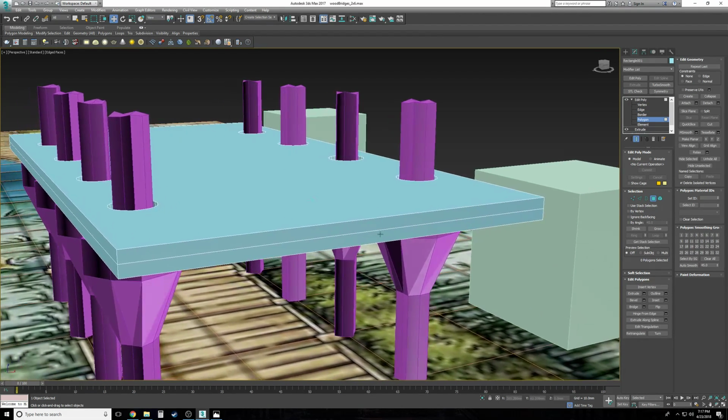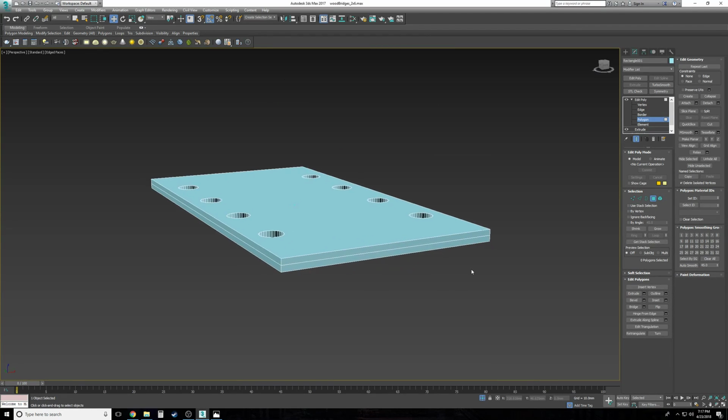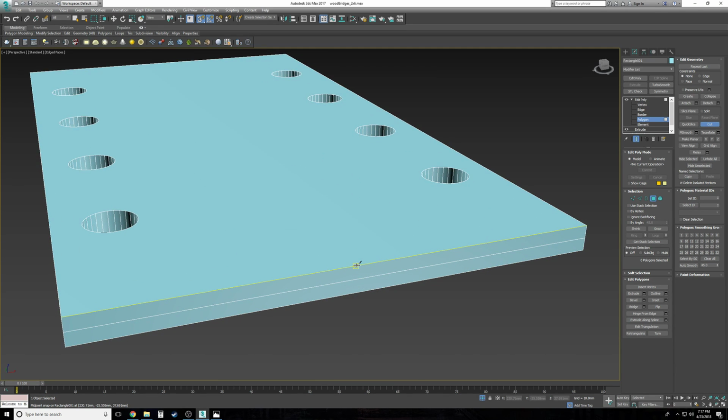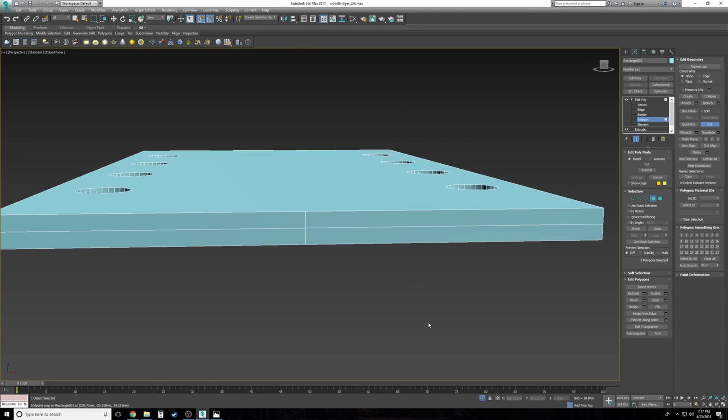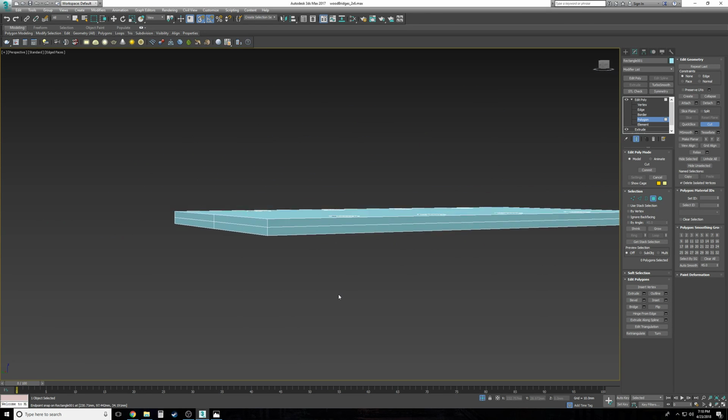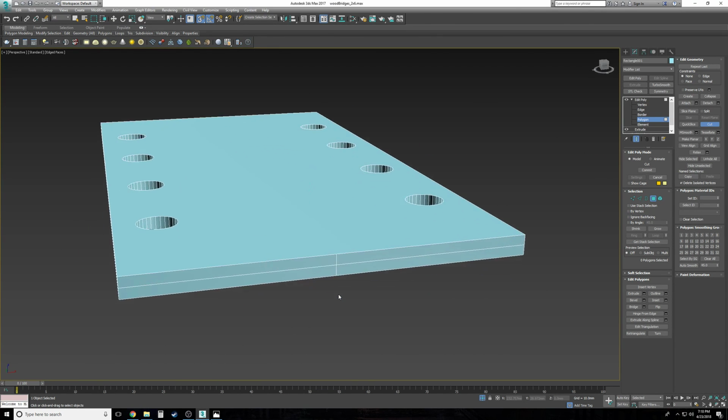And this one we're going to go isolate because we have to cut these things back down to size. Get the cutter tool of your polys ready to go. Turn your snap on. And make sure you're going from the middle to the middle to the middle, like that. Do the same thing for the other side. Middle to the middle to the middle. Oop. Middle to the middle. Stupid thing. Cutter sometimes doesn't like me.